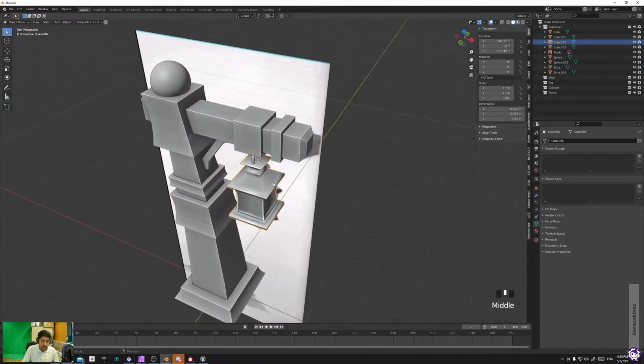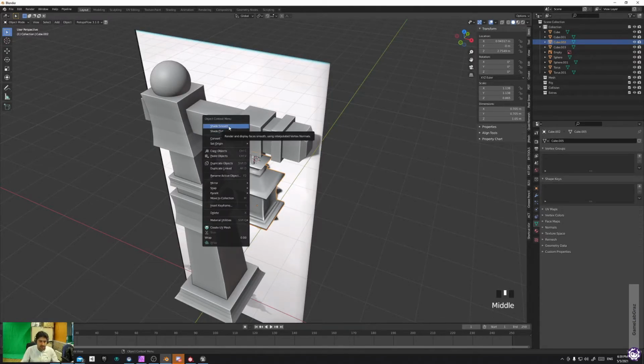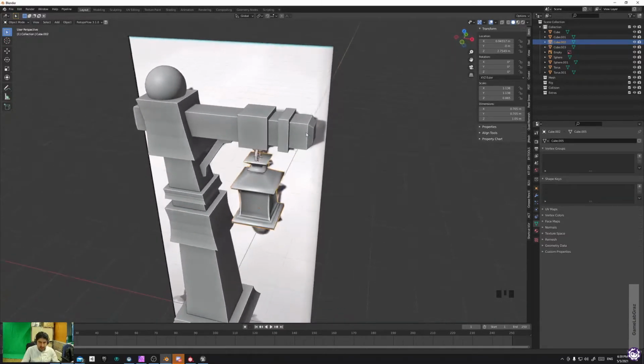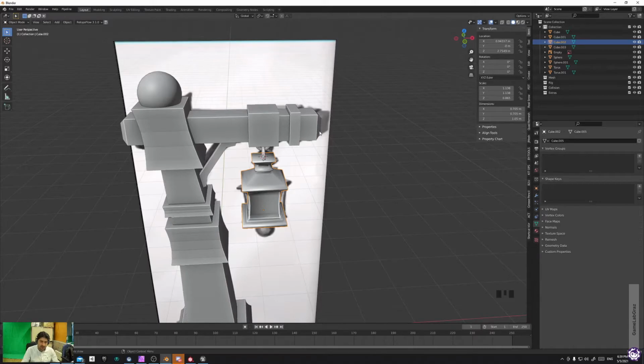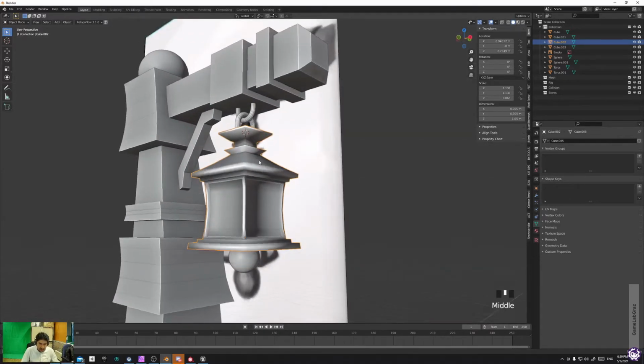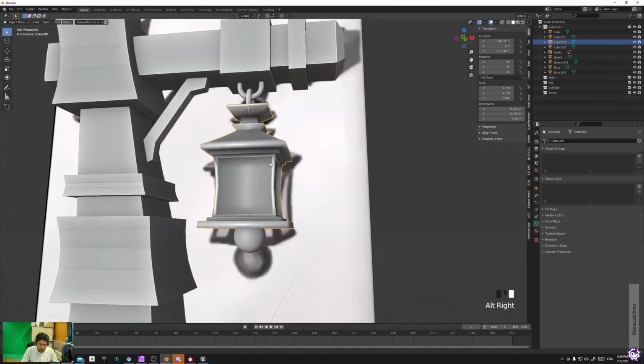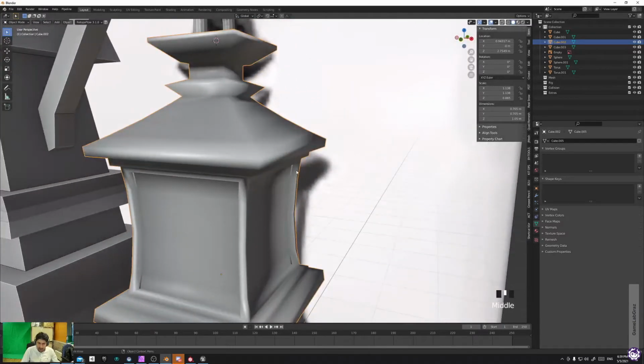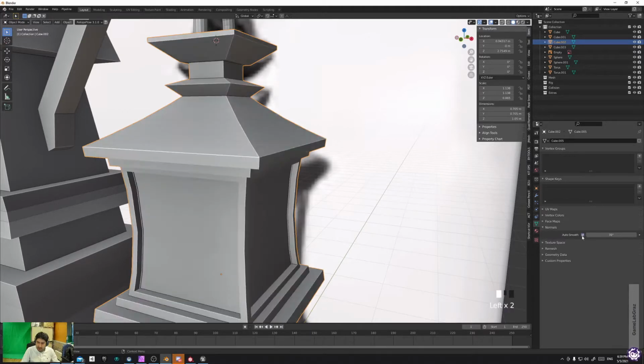Usually you have two options, either shading as flat or shading smooth. The smooth will interpolate between the values of the normals of the vertices and create an average value that causes some smooth feeling to objects. However, if you have some sharp edges, it will create some artifacts. In order to avoid this, you need to go to the object data properties and then select auto smooth.